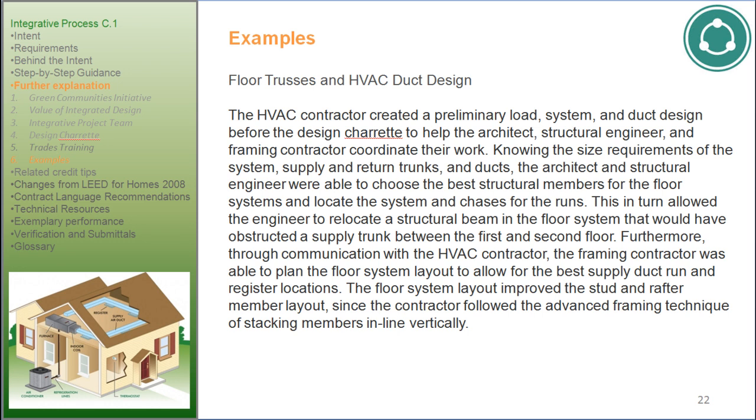Furthermore, through communication with the HVAC contractor, the framing contractor was able to plan the floor system layout to allow for the best supply duct run and register locations. The floor system layout improved the stud and rafter member layout, since the contractor followed the advanced framing technique of stacking members in line vertically.